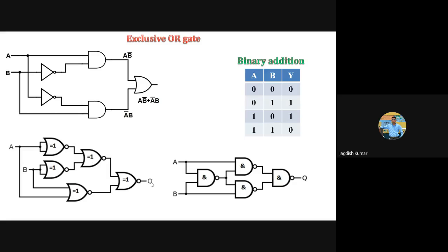So basically, I hope you remember that table for addition of binary numbers. If we have two 1-bit binary numbers, what will be the sum? Okay, you have 0, you have 0, what will be the output? Sum of 0 plus 0 is 0, 0 plus 1 will be 1, 1 plus 0 will again be 1, 1 plus 1 will be 1, 0, but we are dealing with a 1-bit system. So that will be 0. Carry has to be discarded, because if we are dealing with a 1-bit system only, then output will be 0 here.